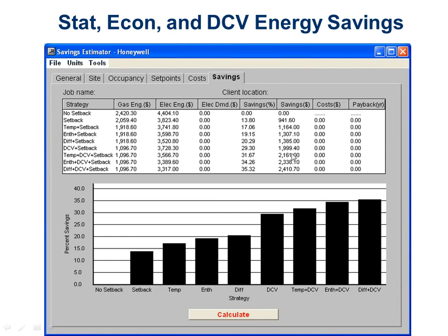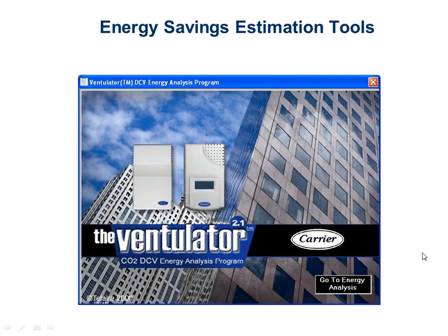The only thing this doesn't do very well is zoning systems. So when we have a zoning system, we use a different tool occasionally, which is a tool developed by General Electric, by Telair, which in this particular case is branded as Carrier Tool. But you can do single zone or multiple zone systems with this. It's a little bit more of a complex analysis, but it's still fairly easy to use.